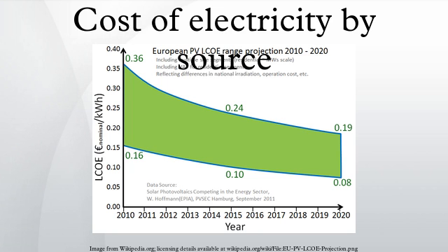Beyond the power station terminals, or system costs, the raw costs developed from the above analysis are only part of the picture in planning and costing a large modern power grid. Other considerations are the temporal load profile, that is how load varies second to second, minute to minute, hour to hour, month to month. To meet the varying load, generally a mix of plant options is needed, and the overall cost of providing this load is then important. Wind power has poor capacity contribution, so during windless periods, some form of backup must be provided. All other forms of power generation also require backup, though to a lesser extent.